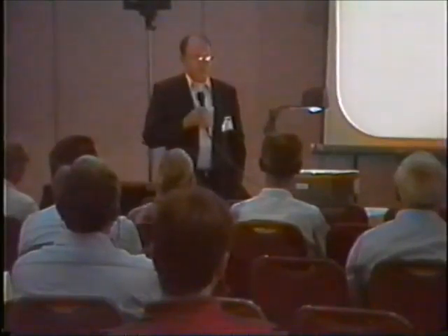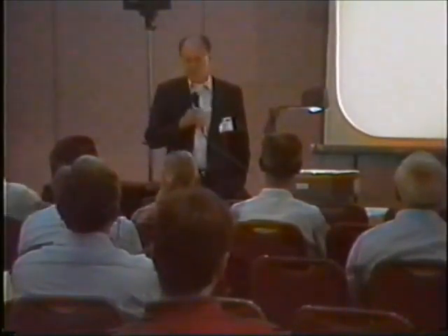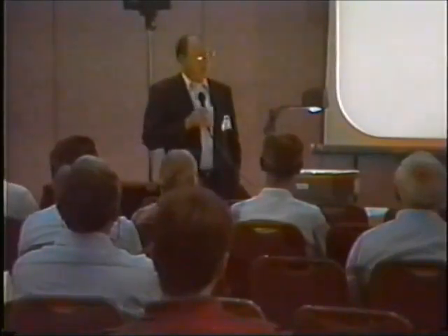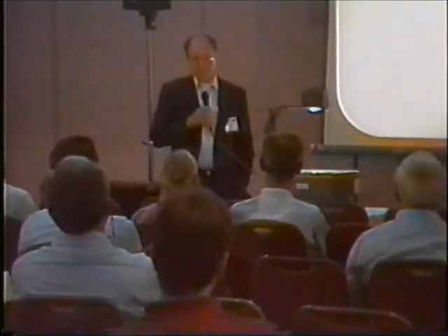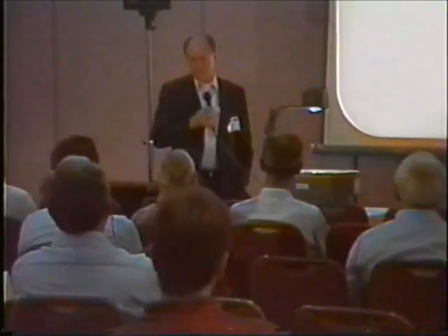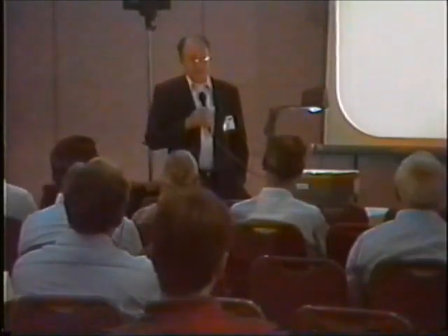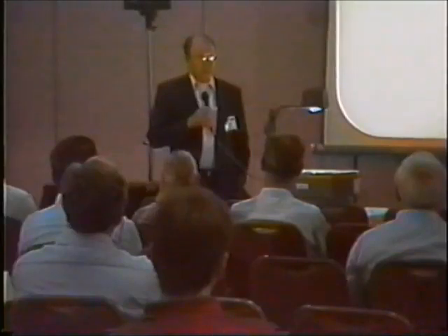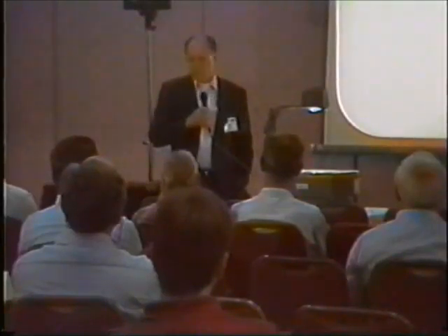If you try to measure it with the conventional systems, I'll show you some after a while, you'll have a resistor stacked as high as this ceiling here and then some, in order to divide the voltage down to where you can measure it with your instruments. And that gets to be very complicated. It's also very dangerous. So it's much easier to use the magnetic flux, which is the actual other side of the coin, but it's not dangerous like the electrical flux. Okay.